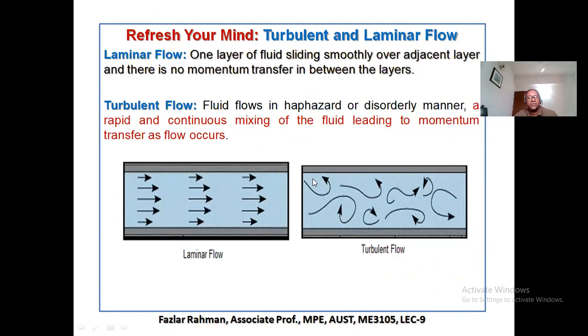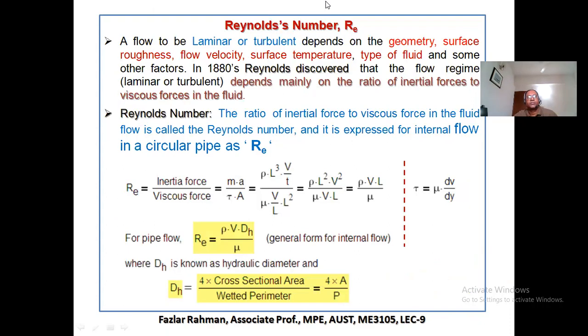By mistake, I put the definition of turbulent flow in again. Now, you see that we need to figure out when flow becomes turbulent and when flow becomes laminar. I already told you that it depends on the Reynolds number. Then you need to know how we figure out a Reynolds number, and you need to know the range. For example, you might say for Reynolds number 10 to 20 flow is laminar, over 20 is turbulent. I just gave you an example. The 20 is your critical point. Instead of 20, it might be 200, it might be 2000, right? So before that, we need to know what the Reynolds number is, what it means, and how we can figure out the Reynolds number for a fluid flow.